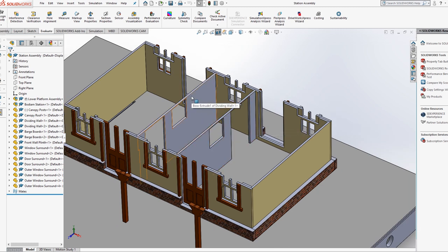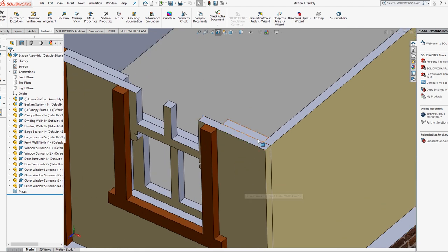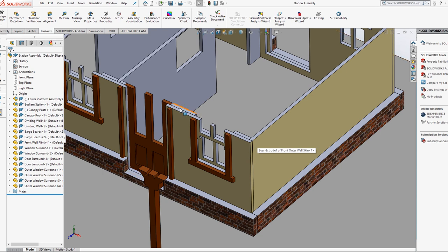so that we can put a camera inside. Anyway, the takeaway from showing you this really is that each of these pieces that I'm showing you are essentially two-dimensional. Certainly all the dimensions are 2D, and the thickness is accounted for, this 1mm thickness, by the thickness of the material itself. So in terms of the drawing that we would need to produce this, it is just a two-dimensional drawing which could be sent to the laser cutter. And we'll look at this drawing in a bit more detail in just a moment.